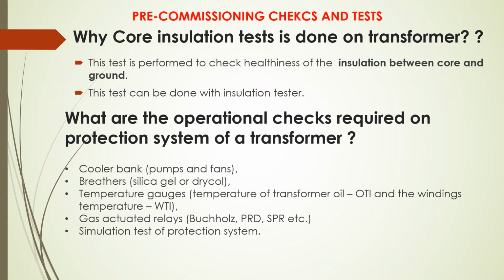Why is the core insulation test to be done on a transformer? This test is performed to check the healthiness of insulation between the core and the ground. This test can be done with an insulation tester.